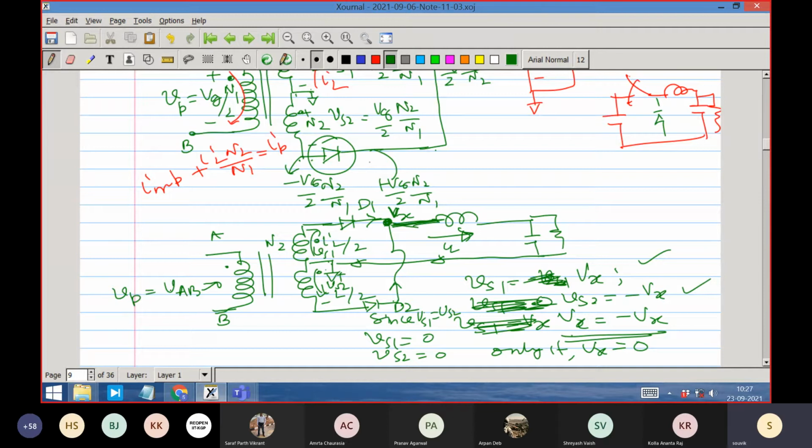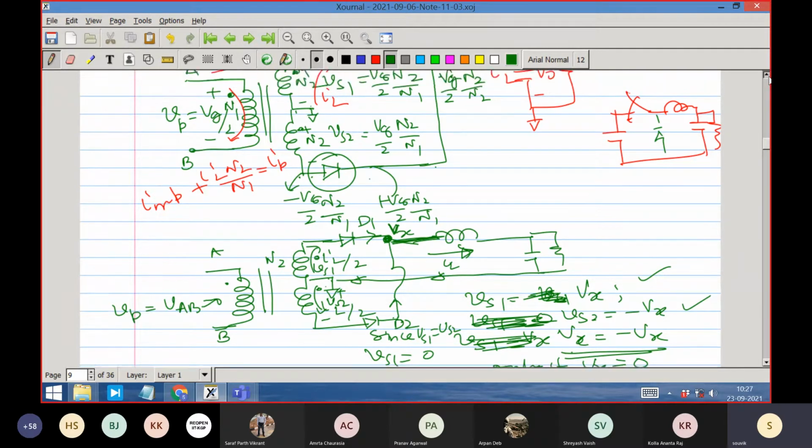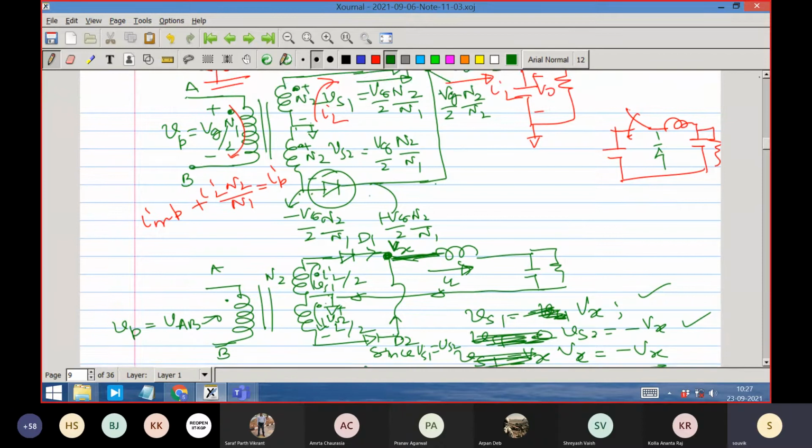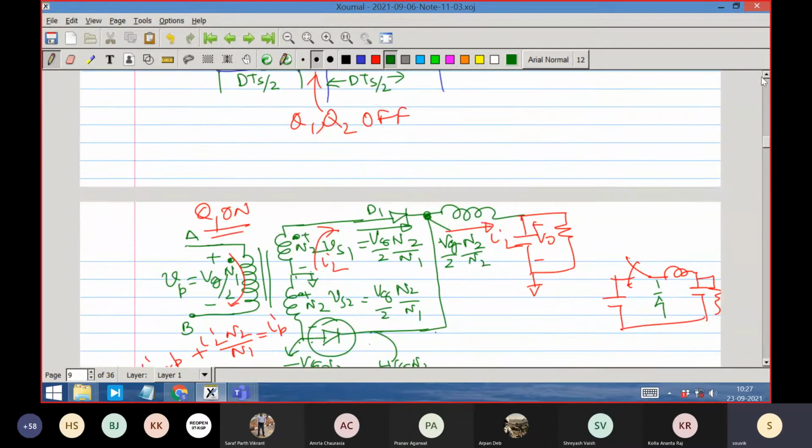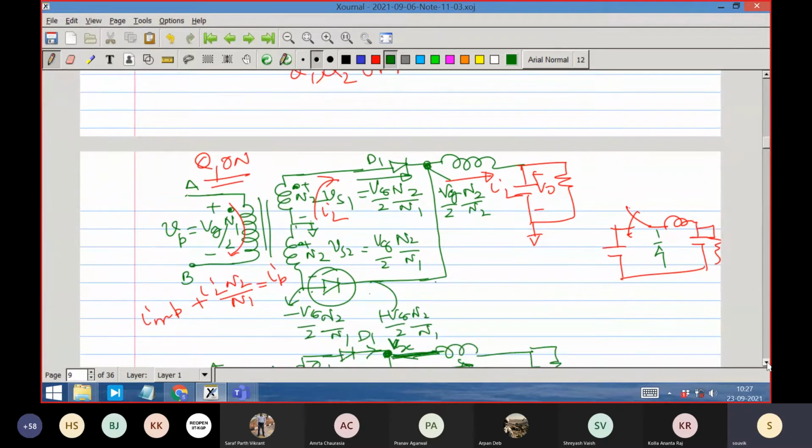That is how the voltage is imposed on the primary. It is imposed from the secondary side, and it is imposed by whom? Actually, who is the cause? The inductor current continuity. The secondary side inductor current is continuing, and we have cleverly done a structure such that we use two diodes for freewheeling, and this two-diode freewheeling is imposing the secondary side voltage to be 0.